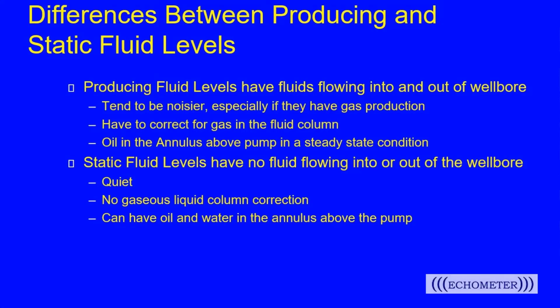So once the well's truly static, there will be no more fluid flowing into or out of the wellbore. And in this presentation, you'll see a slide that shows the transition between a producing case and a true static case. But once it's truly static, we won't have any fluids flowing in. So it'll be quiet. We won't have a gaseous liquid column anymore because there will be no more gas coming into the well. It'll be a solid column of liquid.